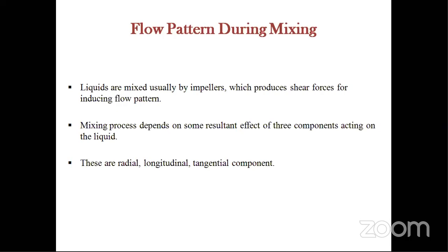The shearing force or applicable force helps in liquid mixing when you are going to mix several components, two components or more than three components. During application of shear forces by impellers, whether your components are solid and liquid, or both liquid, or viscous liquid or less viscous liquid, depending on whatever component you take in this mixing process, you have to maintain some flow pattern, or automatically this flow pattern is maintained when you apply the shear forces by impellers.